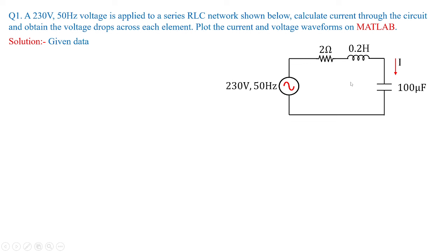Okay, first you take the data which is given as it is. RMS value of voltage is 230 volts. Just to remember, friends, whenever these kind of questions are framed, 230 volts, whatever the value is given as an AC input voltage, its value is actually in terms of RMS value. We can convert that value into the maximum value or instant value based upon our requirement. Okay, so we have to consider 230 volts as RMS value,